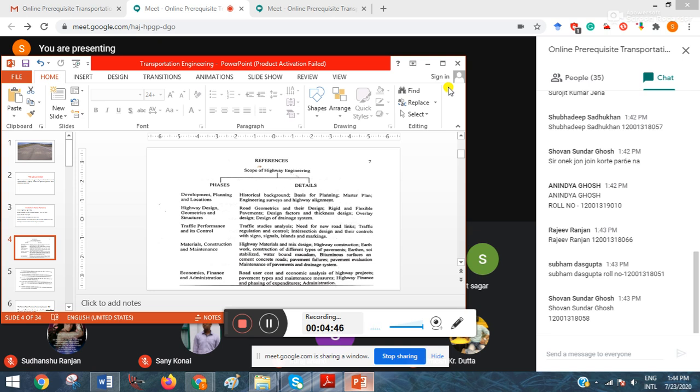The road or roadway thus constructed is therefore termed highway, and the science and technology dealing with road engineering is generally called highway engineering. Again I am repeating, the road pavements are generally constructed on small embankments. Embankment is the deposition of some soil, which is known to us from our soil mechanics class, slightly above the general ground level wherever possible, in order to avoid difficult drainage and maintenance problems. Drainage is an important part of the highway to protect against moisture, differential settlement, and loss of stability of the road. The road or roadway thus constructed is therefore termed highway, and the science and technology dealing with road engineering is generally called highway engineering.